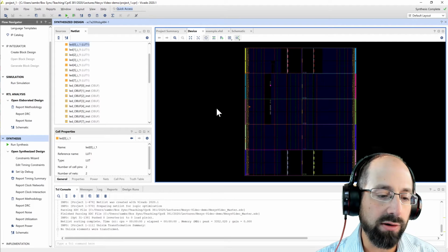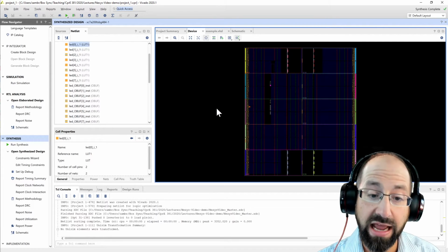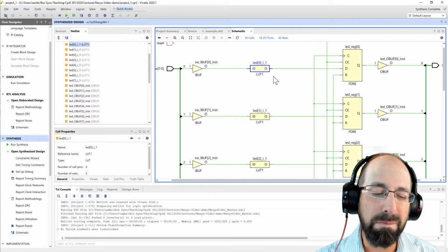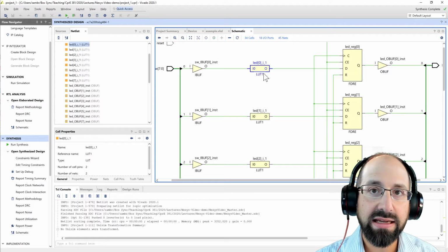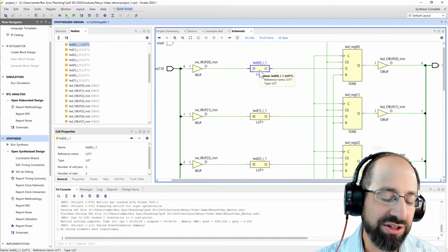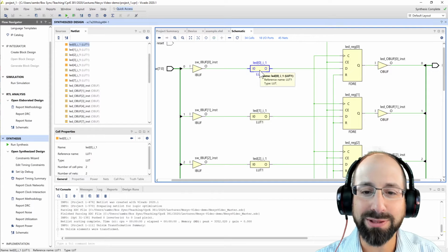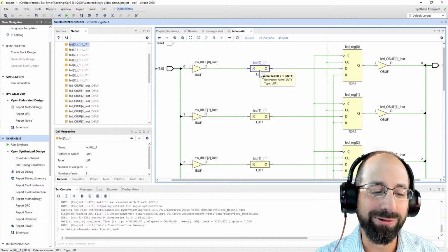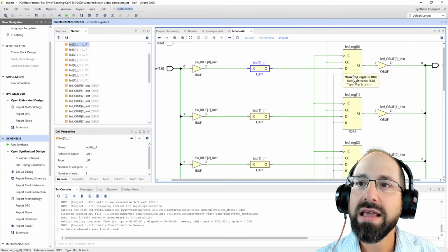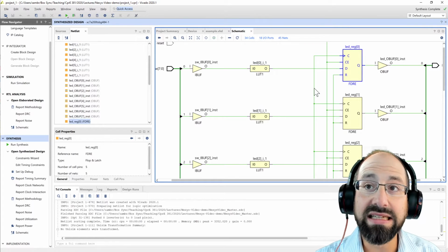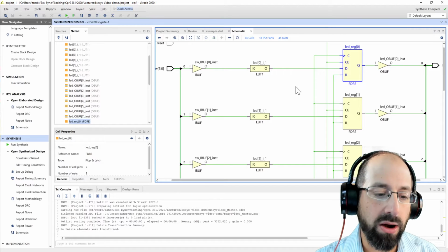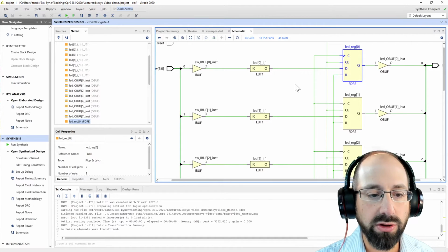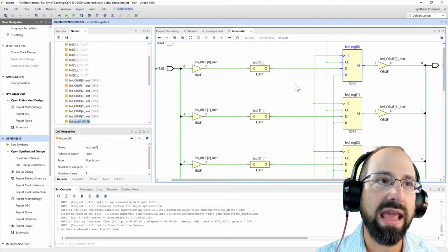That is the first part of what we call logic synthesis. And for an FPGA, for the logic synthesis, your result is going to be in terms of the built-in things that are on that device. That's a LUT1, a one input lookup table. It's an inverter, right? There are only so many options for a one input lookup table. It's either a pass-through or an inverter. That's all you can really do. There are also little flip-flops that are part of that computing fabric, and it's mapping that register we saw in the behavioral model to those individual flip-flops that we have there.